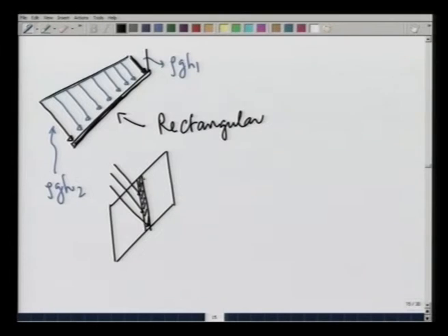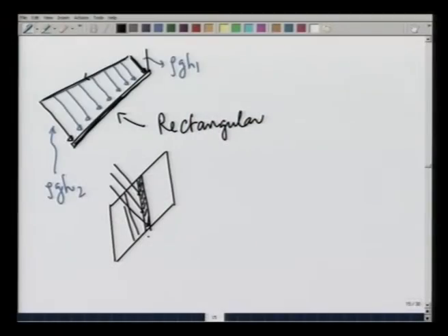If this were not rectangular, the force at different points would vary according to how the area changes. So, now the force depends only on the depth, because the area for each strip is a constant. So, then loading becomes linear. So, now we are being restrictive to rectangular sheets. So, let us see now the force acts at the centroid of this trapezoidal loading.